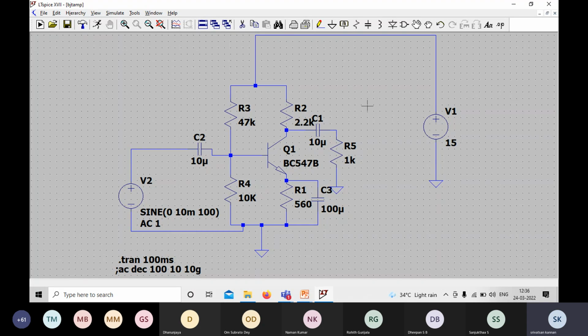For bandwidth calculation, see, we plotted the frequency response of a band pass filter. So how is the bandwidth calculated in the band pass filter? The difference of the frequency ranges. Yes, higher cutoff frequency minus lower cutoff frequency.